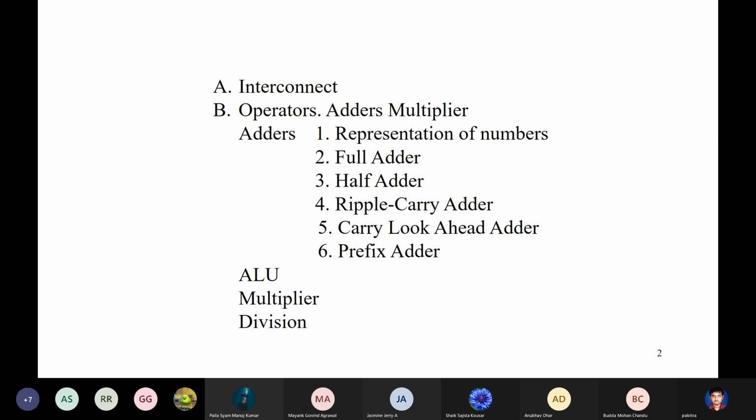And this kind of shift register is also very commonly used in multiplication, because you can write multiplication as a series of additions with changing positional values, tens, 2, and 2 squared, and you change the value, add it, and you get a multiplier. Maybe we will not go into multipliers and division elements. Maybe you will do that in your next course. But some basic blocks which are there inside an ALU, we'll discuss.